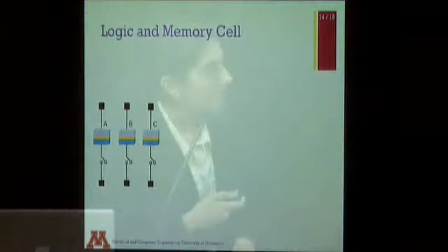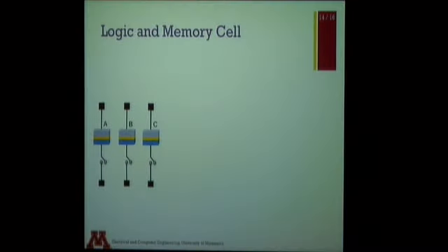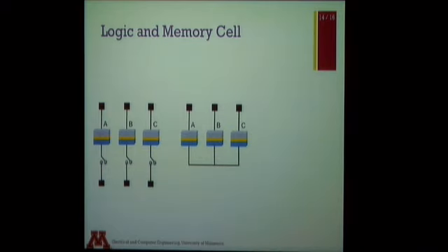This particular structure here is the very classic 1 MTJ, 1 switch circuit in the memory. So this is the single MTJ, single transistor circuit replicated 3 times. And that has a very nice regular structure to it, a very nice memory array-like structure. The logic structure that we just saw was this particular structure, and even that has a very nice regular feel to it.